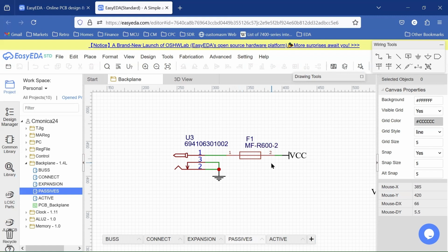Then if we remove the power from the circuit, this would cool down, and again the resistance would go low, and you could plug in your circuit again, but you would obviously look to rectify the problem. So those are two forms of overcurrent that we're protecting from: the circuit drawing over 6 amps, just as the nature of the components, and second, if there's a component failure or a short circuit.